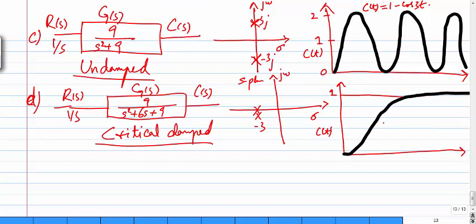The relation for critical damp is 1 minus exponential of minus 3t, because of the step input, and minus, sorry, there's a t as well because of the repeating root, so we have minus t times exponential of minus 3t. So this is known as critical damp response. These are the 4 possible responses. The fifth one is unstable. We are not interested in unstable.